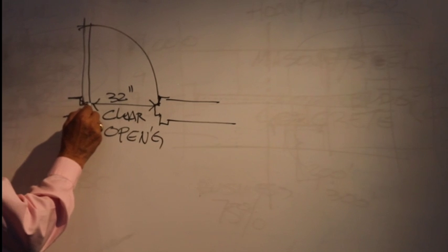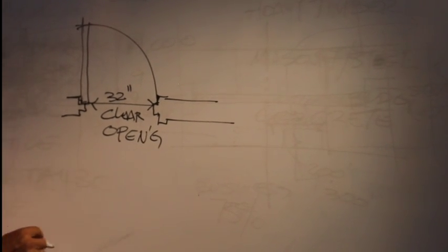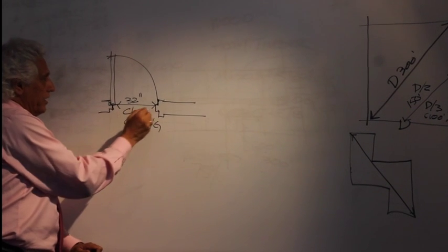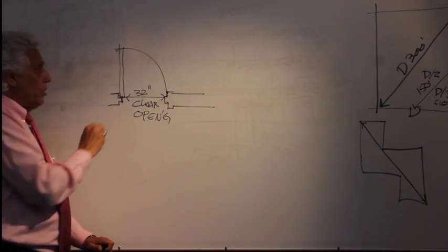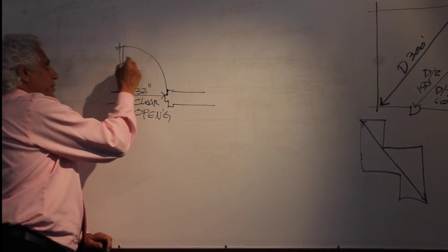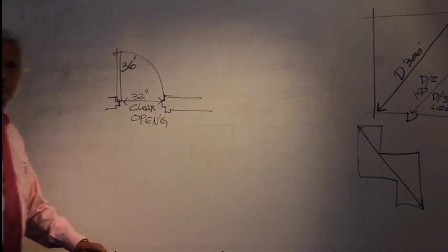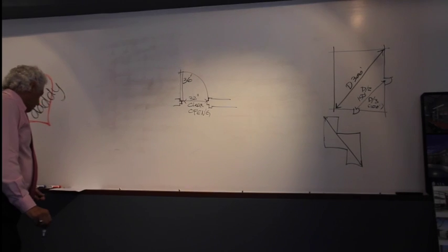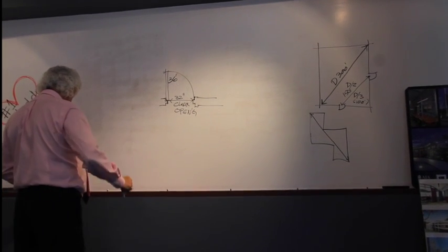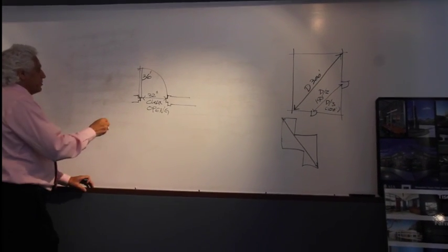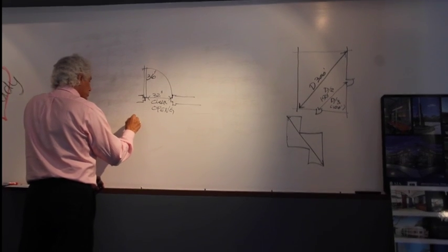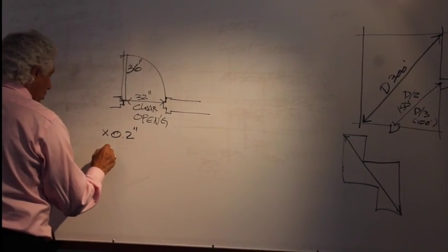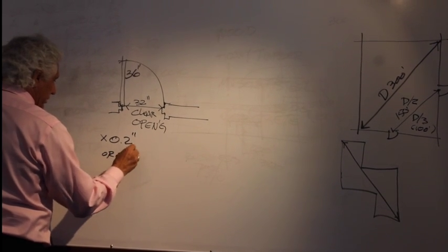When you have a door, and if it's in a 90 degree position, because it has a door closer on it, you have the thickness of the door to take out and the stop. To accomplish that, that's why you have 36-inch doors, because they will give you 32 inches of clearance. When you start determining the occupancy, it's a multiplier on the code of either 0.2 or 0.3.